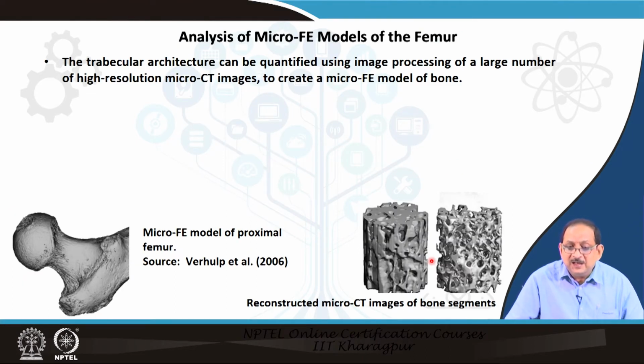Let us consider the analysis of micro-FE models of the femur. The trabecular architecture can be quantified using image processing of a large number of high resolution micro CT images to create a micro-FE model. The reconstructed micro CT image of bone segments are presented here in the figure, and a micro-FE model of the proximal femur is also presented on the left hand side.